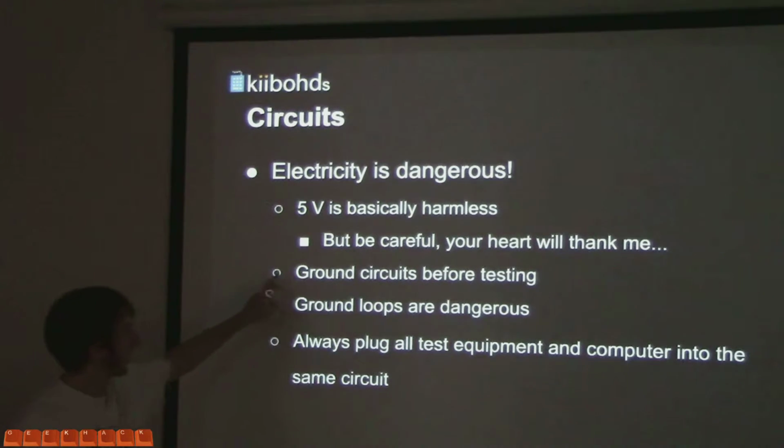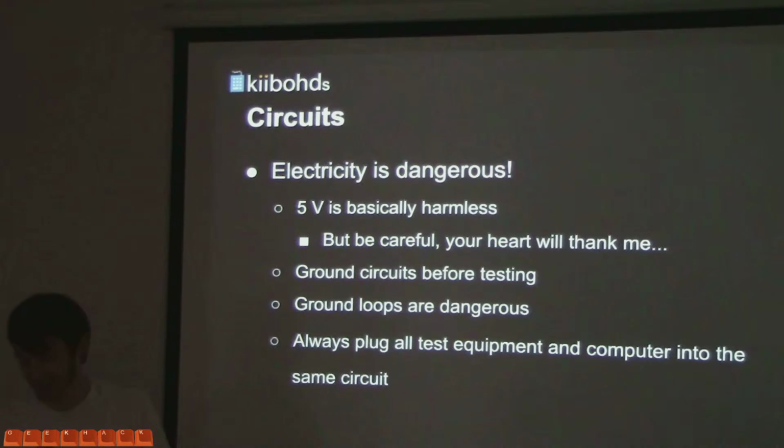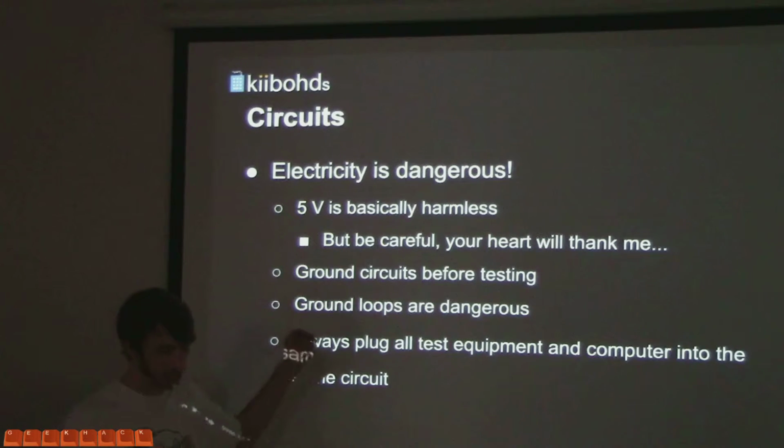Ground circuits before testing, but ground loops are dangerous. I'll try to explain in a very few sentences what a ground loop is. If you have 2 circuits, so if you're testing and you have a computer, make sure those are plugged into the same plug. So we're going to talk about that physical earth. It is ground, or this base signal. So say your base signals are in 2 different buildings. My university had this problem. They do these demos. If you had 2 extension cords from 2 different buildings, your physical earth could actually be different voltages. They could differ by like 30 volts, 100 volts.